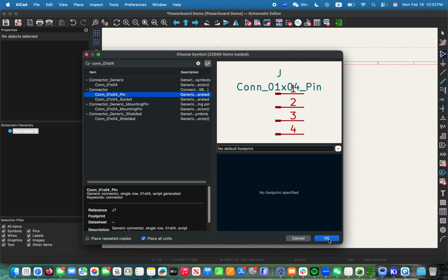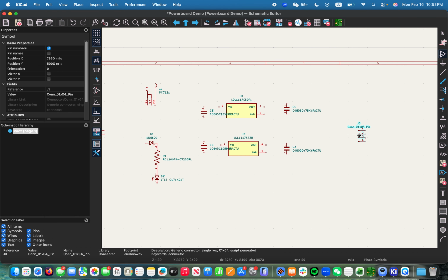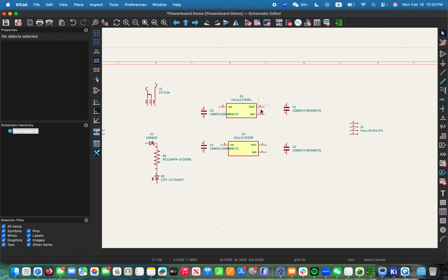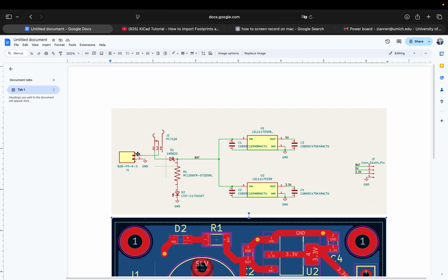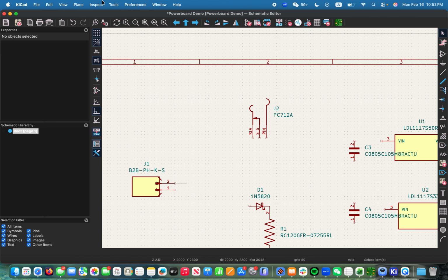And it's the pin here. And then I believe we rotate it. Yep, let's rotate that a little bit. Now in your actual schematic, you don't have to make sure everything rotates. As long as they're connected correctly, that is perfectly fine. So now let's start. We know that for the batteries, we have positive on pin 1 and ground on pin 2. So let's add the ground there.